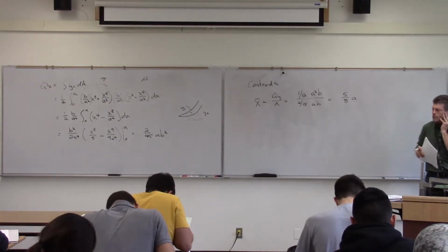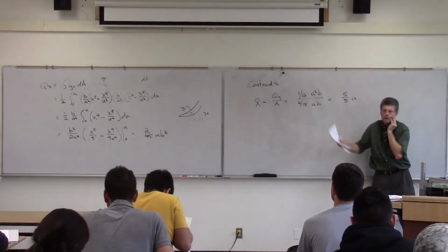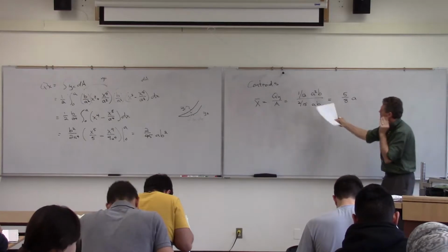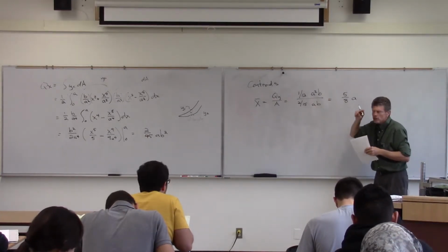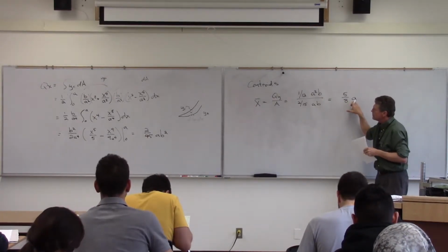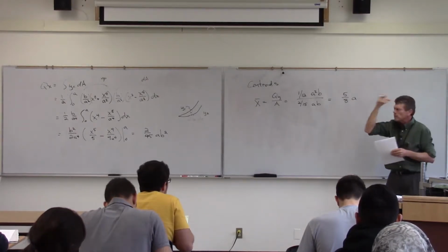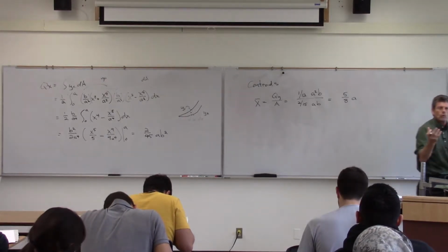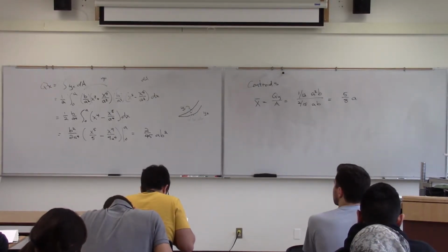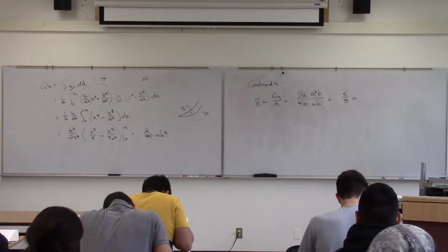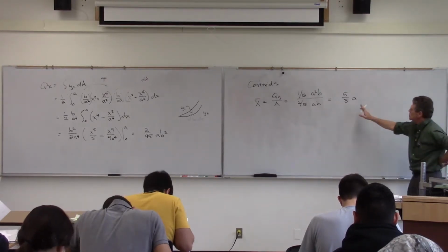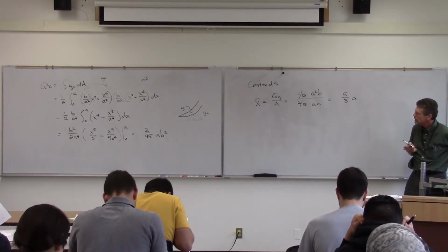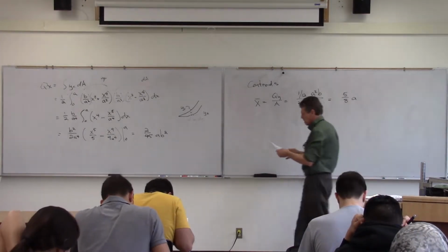And what we do is just simply take that first moment of area that we calculated through the integration there, just like we did with the composites, divide it by the area, and notice that we'll have an a squared there, so that'll be the one thing that's left over. And it makes sense. You need to think about that. The x direction has been given to us, remember, in the a direction, so there's no component of b. We should not expect to see a component of b there. So it's basically telling us in relation to x equal to a, 5/8 over is going to be where the centroid of that particular blade area is.